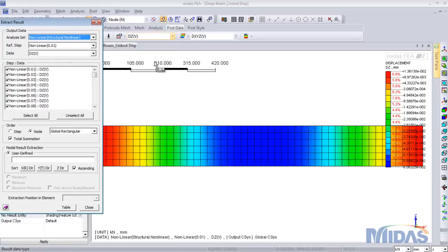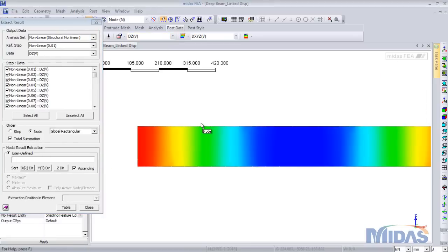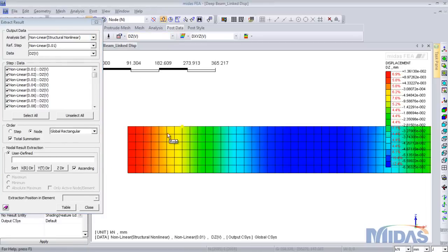So here we are. The displacement was applied at 40 centimeters from the left, so I can see the distances from my bottom status bar, and just simply select it like this, and we will see the nodes are entered here automatically.